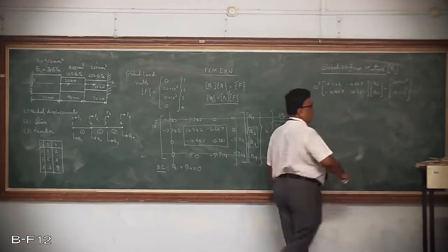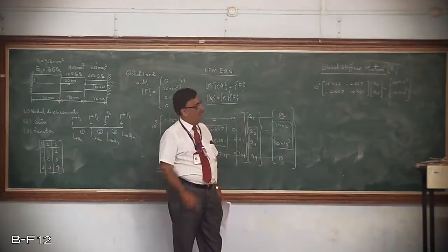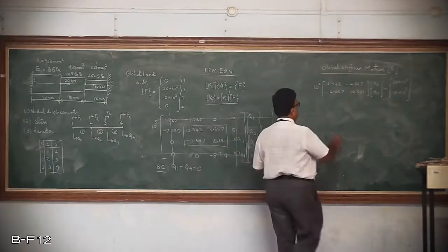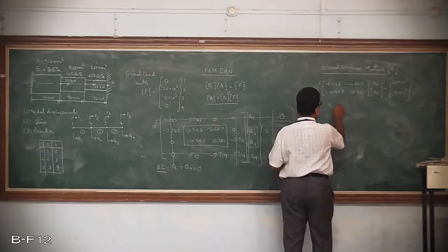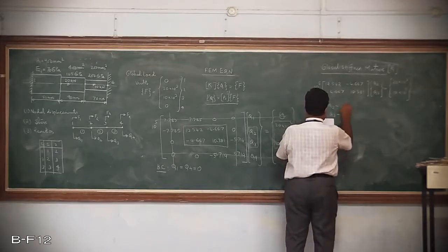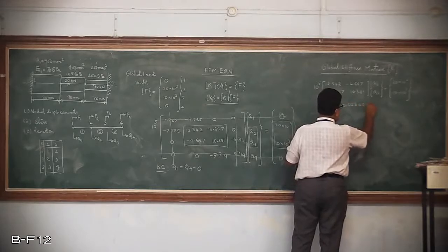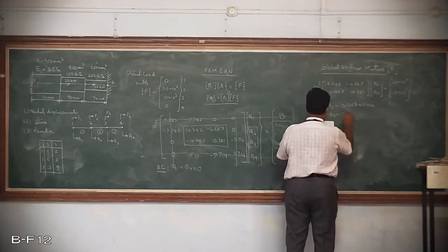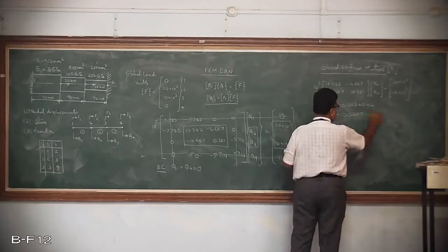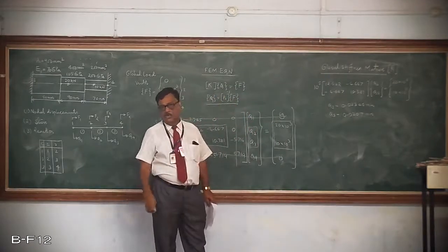So now you will get two simultaneous equations, two linear equations. Solving them simultaneously will give you the values of these nodal displacements. So Q2, after finding the solution, comes out to be 0.02345 mm, and Q3 comes out to be 0.2017 mm. So we have found out the 2 degrees of freedom which are possible here.